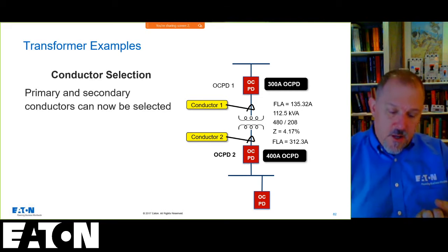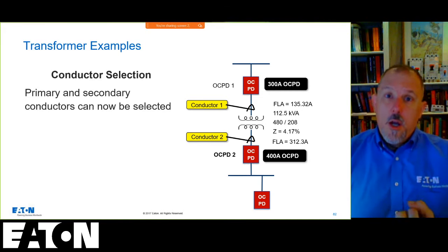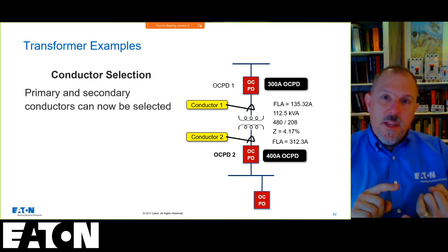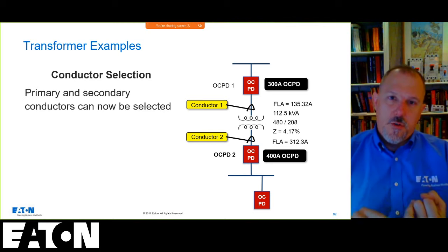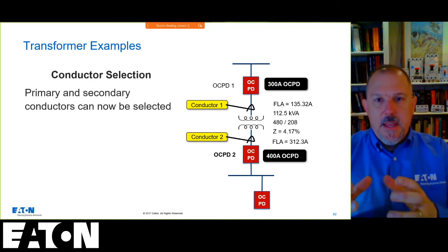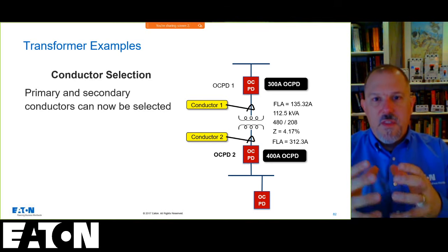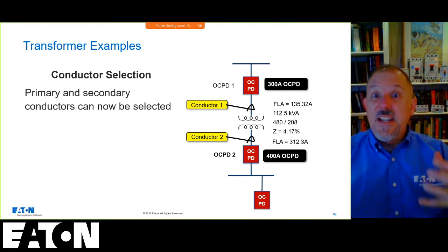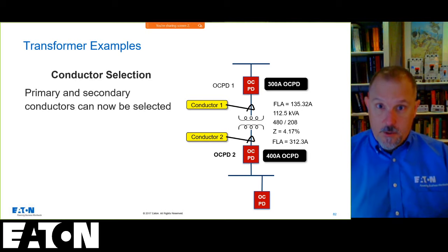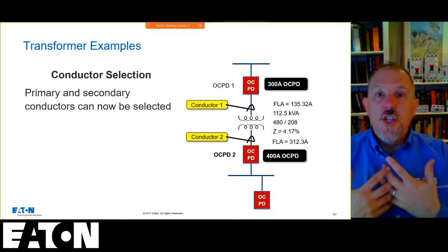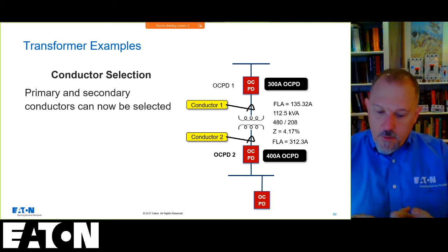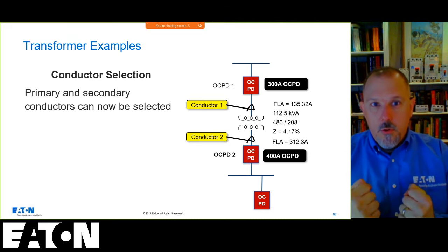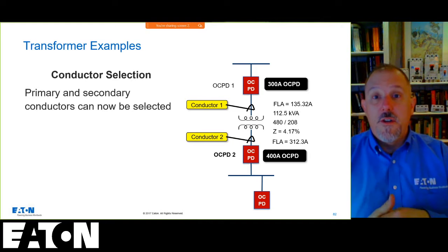What we have for panel boards and switchboards are short circuit current ratings. And what that tells you is that you have to apply that piece of equipment within its rating. It's going to hold it together. It's not going to have an unintended rapid disassembly in the field. As long as you apply it with the right overcurrent protective devices at the right fault current values, it will hold it together while those devices do their job.